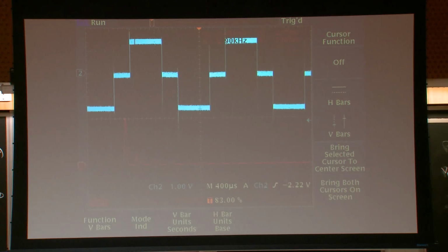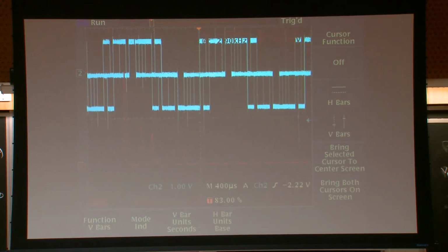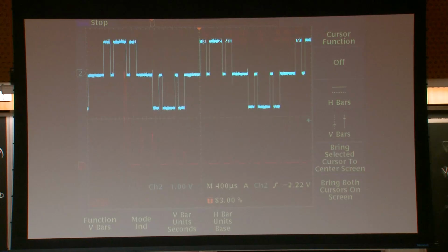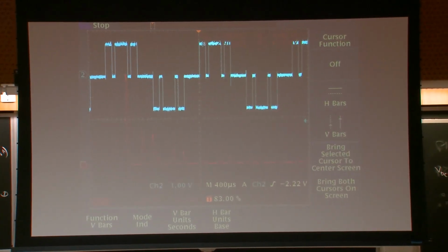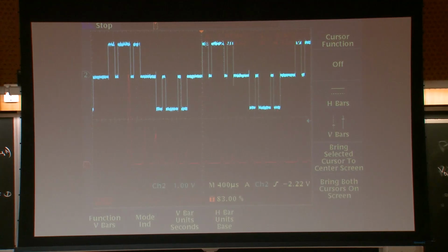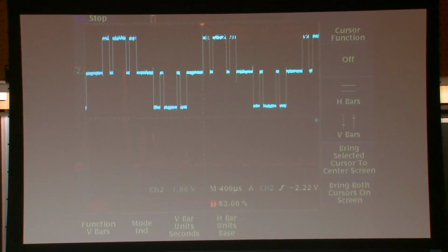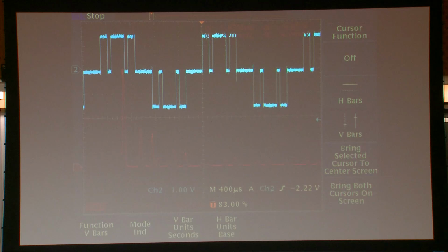Now, let's do another thing. It's going crazy, but let's see. Like we saw in class, if we introduce pulses or notches on both sides of the waveform, it's still half-wave symmetric, so we're still doing the same thing. But interestingly, if we move to the second highest spike, it's at about 4.2 kilohertz, which is the seventh harmonic. So we eliminated the third and fifth harmonics.